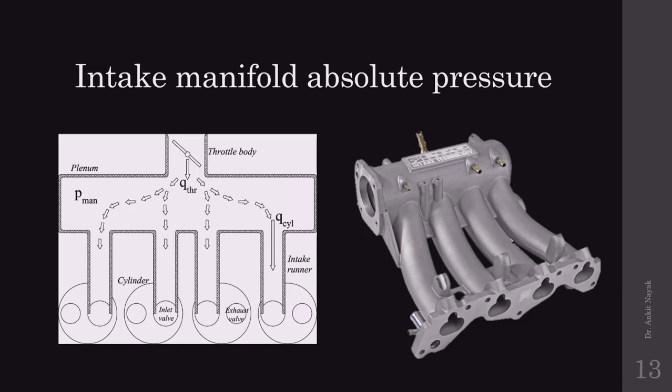We have to measure the intake manifold absolute pressure in such a way that we can supply the proper air fuel ratio inside the cylinder in order to achieve the proper power from the engine. So for the measurement of the pressure, we can use different pressure sensors.